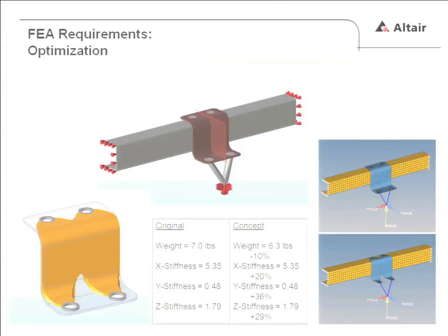And then a quick note on optimization. So a lot of times if you see an FEA guy present optimization, it'll be a fairly complex optimization. So I wanted to go a different way and do something a little bit more basic, like this bracket. And the reason I like this one is because it's so different, is because the weight savings, typically what you look for in aircraft optimization, probably the vast majority of the time you're looking for weight savings, but you could also look for stiffening. You know, if the project requirement change, you might need a stiffened component, and you might not be worried about weight in that case. In most cases, it is weight.